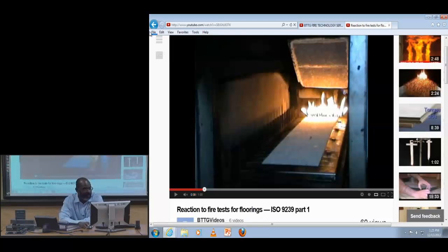So we're going to, again, switch to a video series that's available on YouTube. And this is the reaction to fire test for flooring. So just to guide you through this, what you're seeing is a flame that's an ignition source, a pilot, and what this test does is it measures the spread rate over, in this case, a flooring specimen, with the idea that there is some sort of external heating that's provided by this inclined radiant panel.